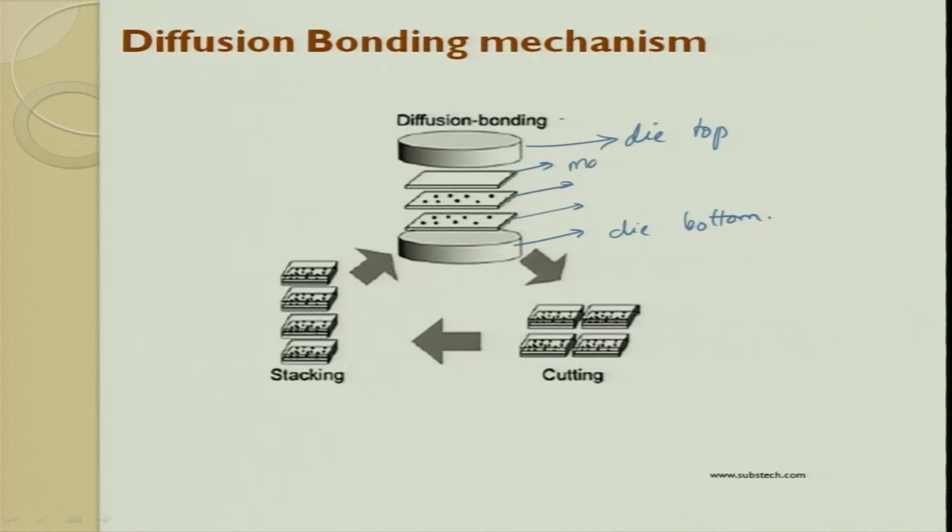So, this can be exclusively matrix, this can be matrix, and then you have dispersed reinforcement. Again, here you can play with the dispersed reinforcement volume fraction. For example, you can have a 10% volume fraction. As and when you keep going, you can have a 30% volume fraction here, and then on top you have a matrix, whatever you want. So, now when you consolidate and develop it, you will have a metal matrix composite which is functionally graded. So, functional gradation can be brought in while making it.